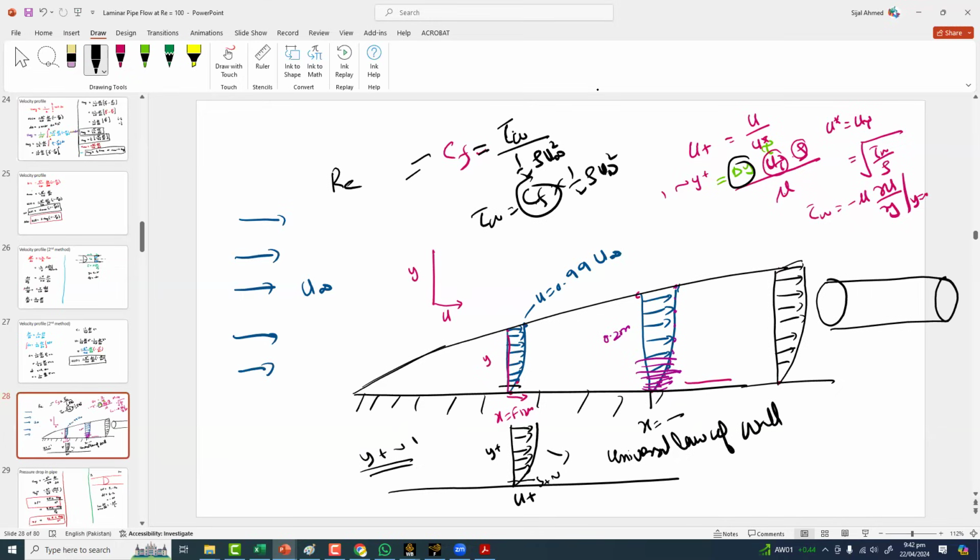For internal flow, we directly take care of it, because mesh requirements are already there: for the geometry resolution, this much should be there, and at this point the flow is this. In internal flow, we have a very small area portion, so we automatically take care of it by the meshing mostly. But for external flows, the domain size is very, very large, and the boundary layer is maybe 10% of the chord length. If we talk about the aerofoil or wings, it's not more than 10% of the aerofoil. So that's why it's a bigger concern in the external flow.